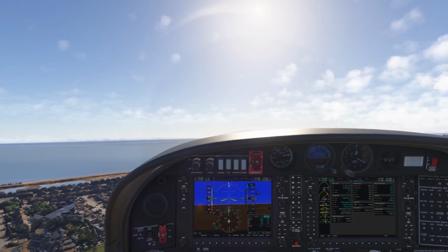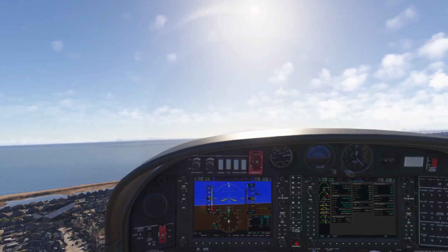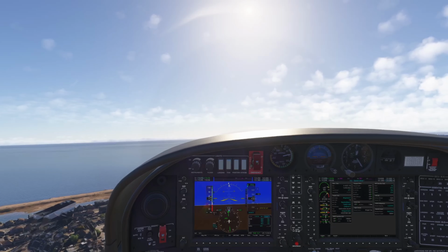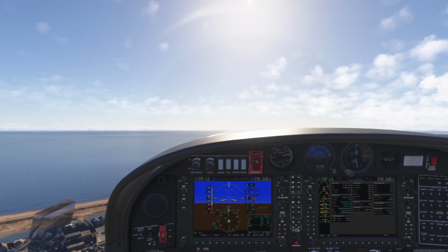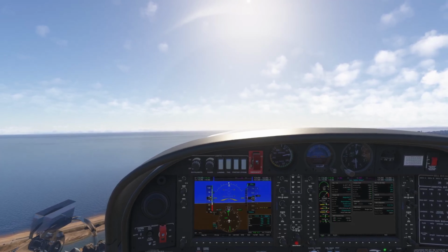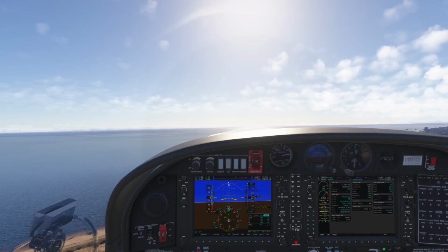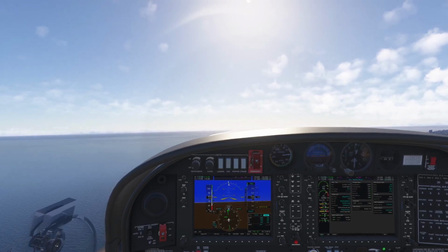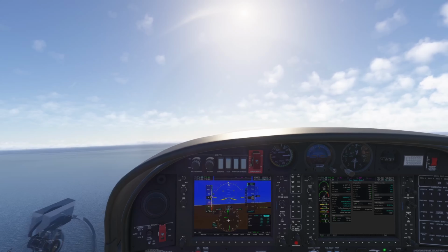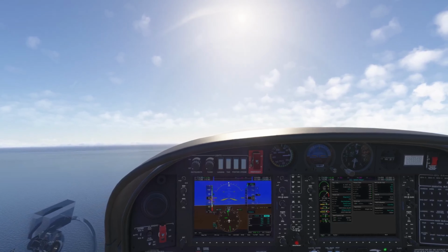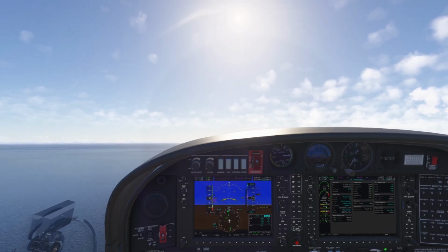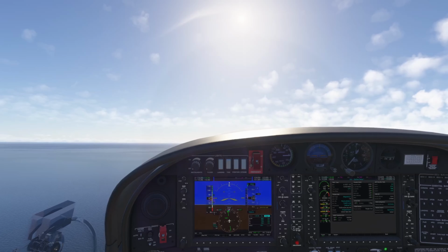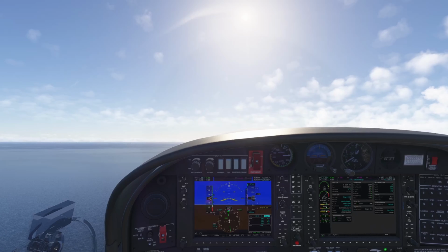Okay, so we're going to reduce back to 90%, turn right by 10 degrees for the power line, 90%, speed check, positive rate, flaps up, and we're just going to let that speed increase to 80 knots now. At 80 knots, we're just going to raise the attitude to hold it, and we're going to trim. So we're selecting, holding, and trimming.